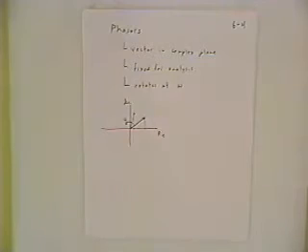And so in fact, if I look at my pen here as the phasor rotating, imagine that it's rotating around. Now I have to think through this. I want it to go counterclockwise as you're looking at it, so I'll go clockwise. And as this pen is rotating around and around, follow the tip of it. But I'm going to continue that rotation, but now I'm going to do it in a plane, so that now all you can see is the tip. And the tip is oscillating back and forth. If I just project the tip into space, it's going back and forth like this. It's tracing out a sinusoidal waveform in space.